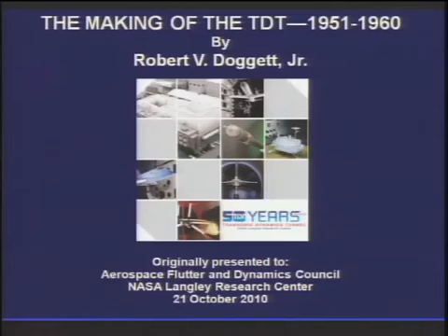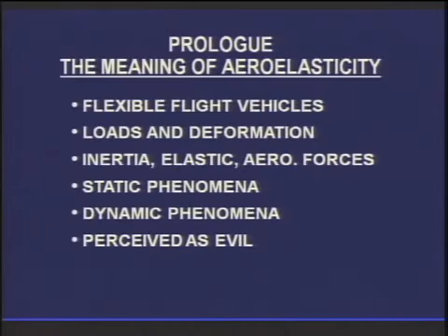There are three types of forces involved in aeroelastic phenomena: the structural inertia, elastic, and aerodynamic forces. Strength doesn't have anything to do with any of this; it's stiffness. And how these three forces combine determines whether it's going to be a static phenomenon or a dynamic phenomenon.